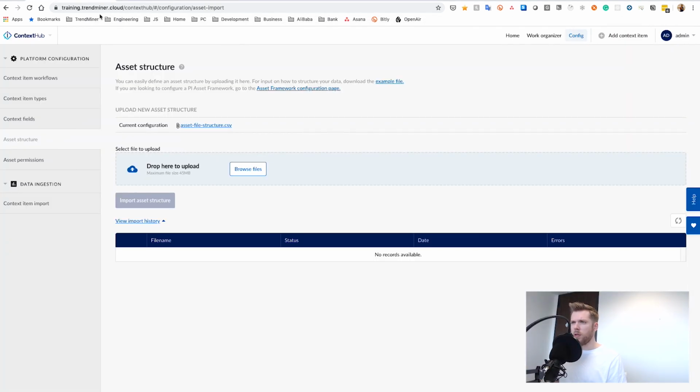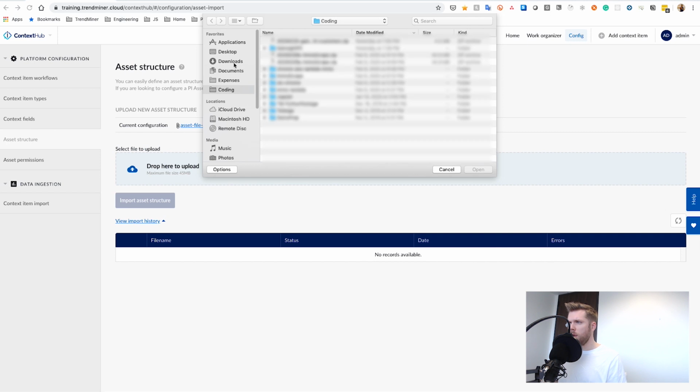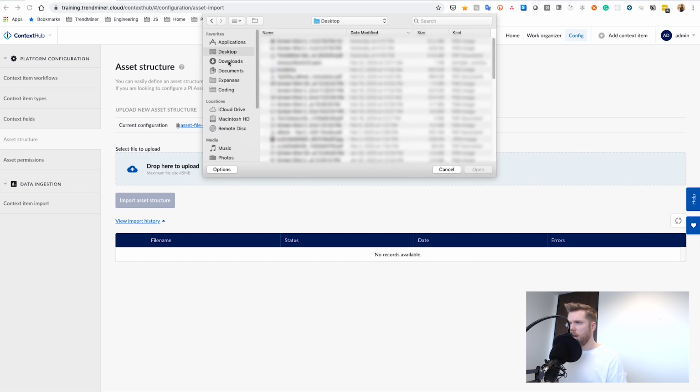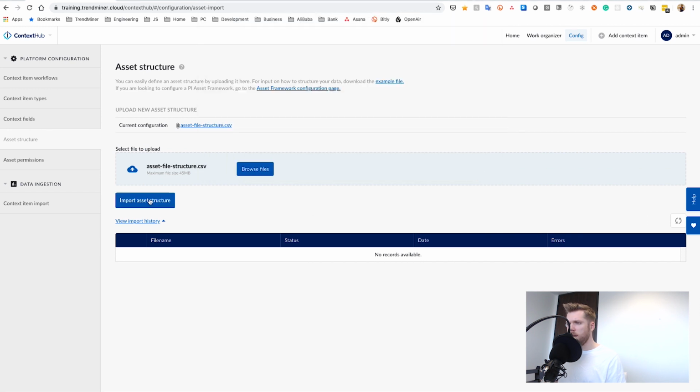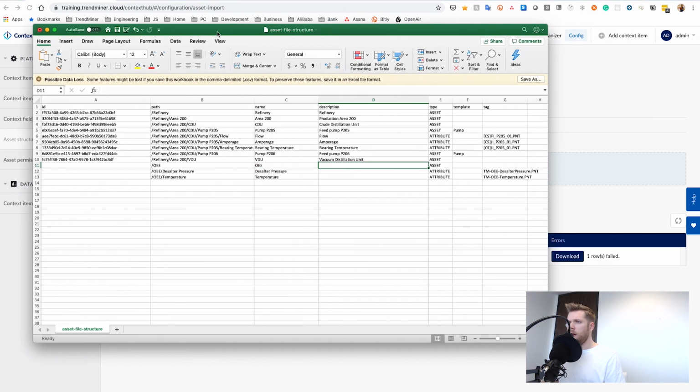Okay, so I've got this file ready. I'm going to load it up by navigating to the right screen, select the file and hit import, and this will take a couple of seconds. As you can see, it's processing. Alright, so it looks like I made a small mistake there. Let's rewind. I forgot to give this OEE element a name, that's why it failed. So I just went ahead and added a name, simply OEE, and I'm going to continue from there.